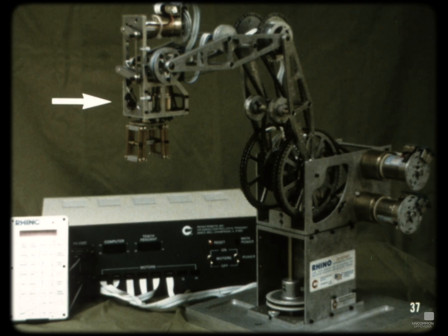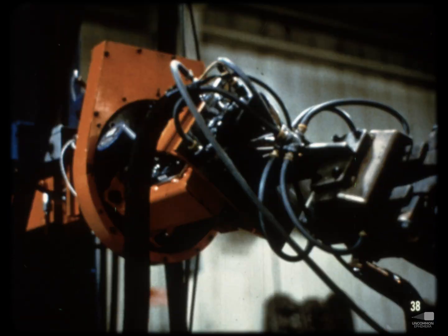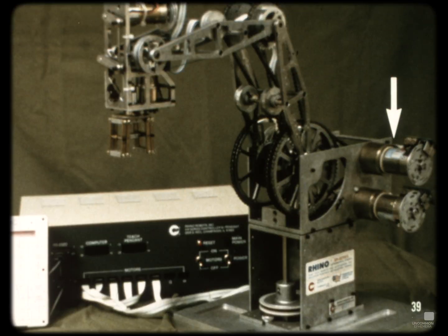Electrical limit switches mounted on the robot's various axes can be used to monitor maximum positional information so that the controlling computer does not force a joint past its physical limit. Pressure and vacuum switches can also be used to relate the position of a robot axis to the controller by creating a proper feedback signal for use in pneumatic and hydraulic systems. The information sent to the robot's computer by a broken photoelectric beam system can be used to inform the system about the actual position of any of the robot's axes.